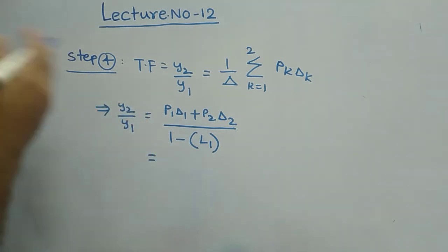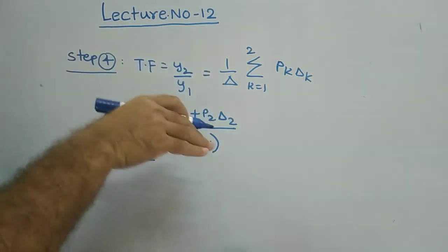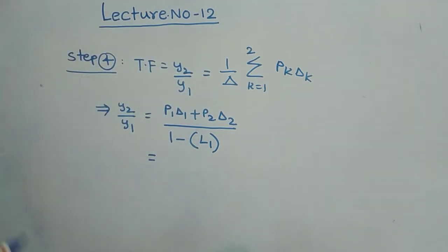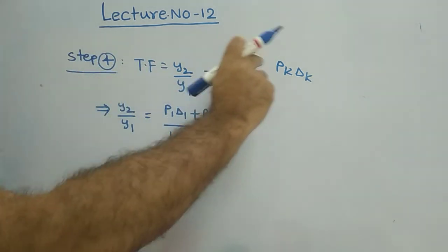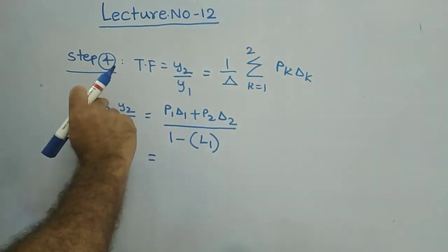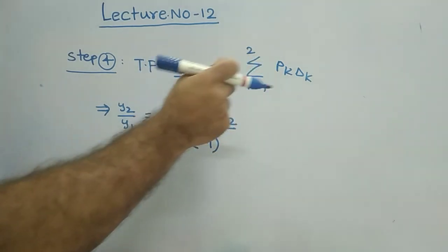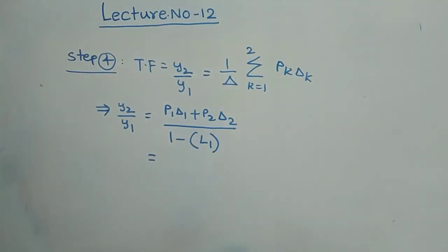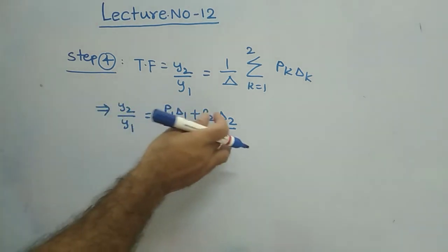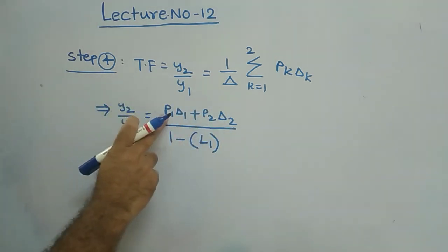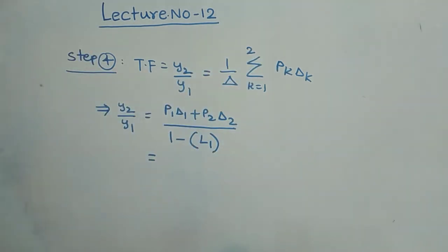so for the given signal flow graph, if any loop is not touching the first forward path, is it like that? You have to identify. For this given problem, for the first forward path A, that independent individual loop C is touching this path at this node, is it not? This loop is touching both the paths. Therefore your delta 1 as well as delta 2 becomes 1, because for the first forward path also that loop is touching. Therefore if it is touching, then the delta 1 value becomes 1.